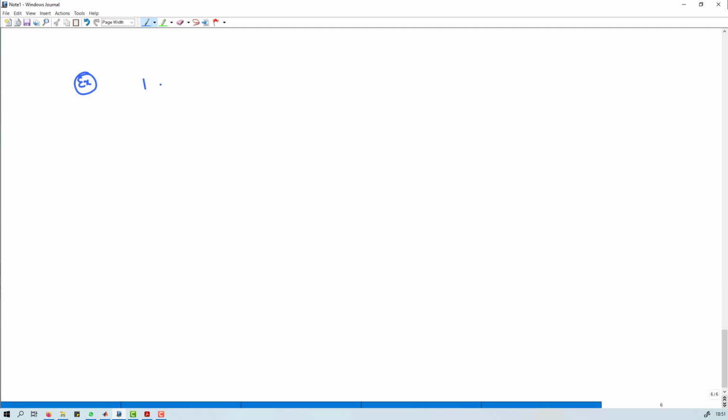Let us solve one more example which is having a zero. So right now we have drawn only with the poles. Now if we are having a zero, what is the situation that we are going to face? Let us take the same thing, 1 by s square into 1 plus s into 1 plus 2s, but having a zero of 1 plus 4s. Now we will write both the magnitude and the phase for the same thing.